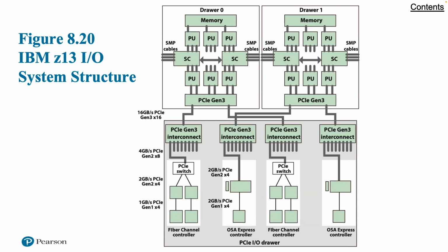The system consists of two large bays called frames, bolted together, that house various components of the z13. The A frame houses 4 processor drawers, interconnects via Ethernet, and one PCIe I/O drawer, which contains I/O hardware, including multiplexers and channels. The A frame also includes 2 support servers used by a system manager for platform management, battery backup, and a cooling unit. It can use either water or air.